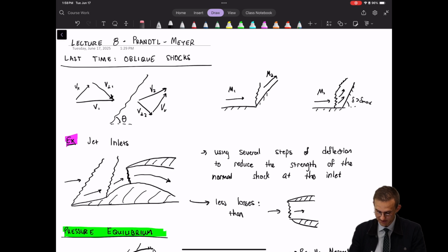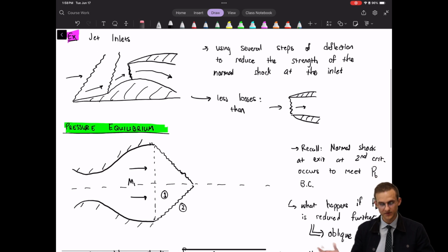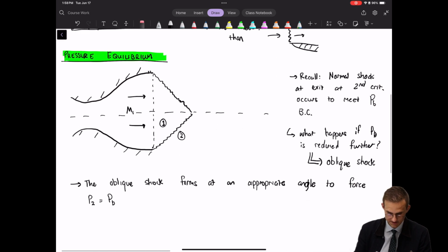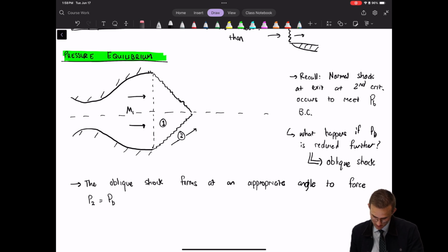So same with this, you can see in this picture here, when the flow is directed upwards, the oblique shock is tilted in that way. So the flow is always directed towards the shock plane, and so the second flow is going something like in this direction, like that. Okay. Let me draw that a little bit better, like that, and that's not an M2.